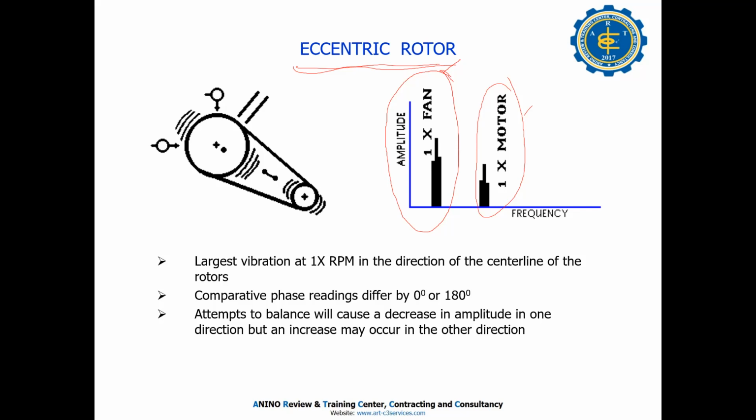The good thing is you're saving time by not collecting data in all the directions. You're just collecting in one direction and you're getting the data for axial, vertical, and horizontal. That is the only thing, you're saving time. And you're safe also because you're not using wires, you're just using the wireless accelerometer. So there are advantages, also disadvantages, but it's up to the management.